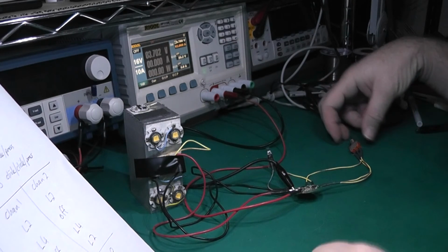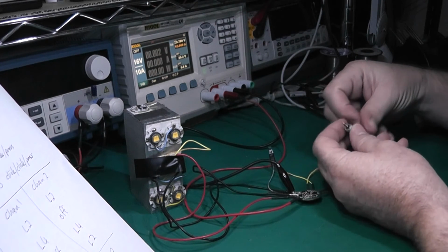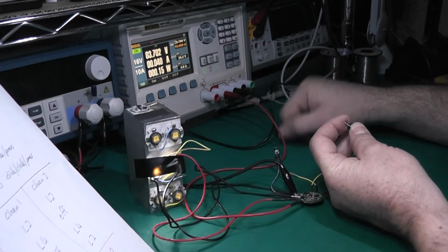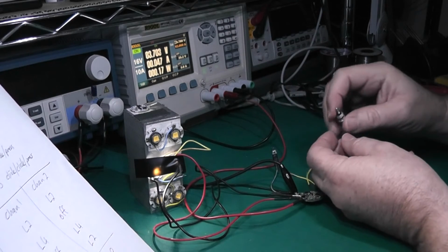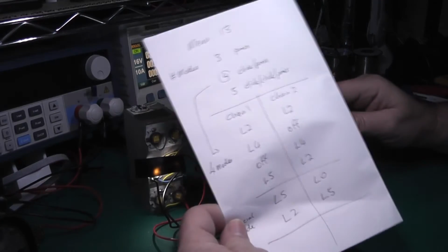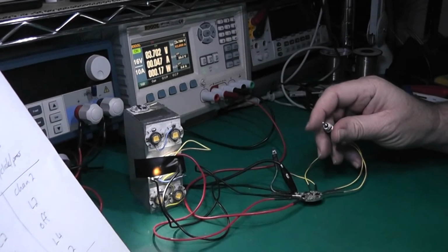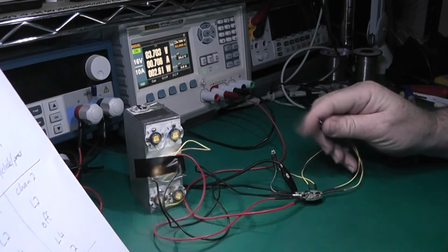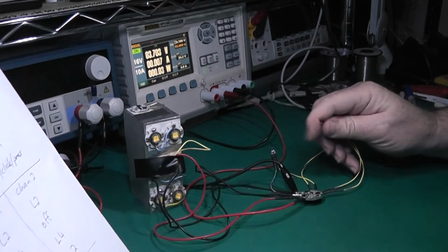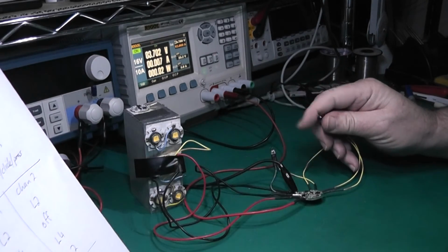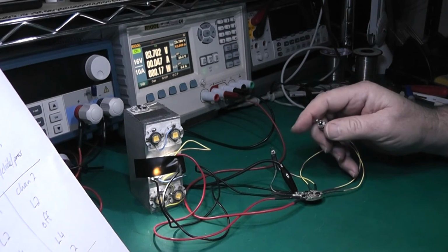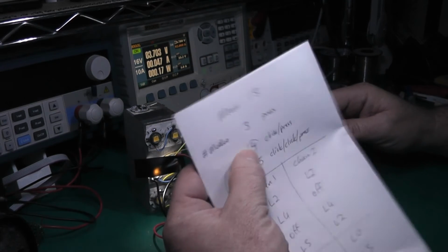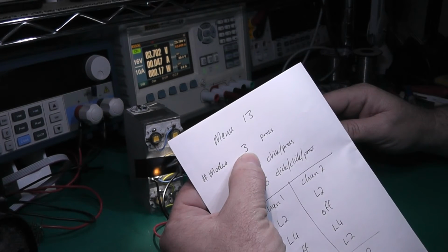So to get into the menu mode, we turn off the power, we press and hold the switch, and we apply power, flashes. We're in the menu system, so we want to program, remember, menu number 13, so we'll do 13 clicks, 1, 2, 3, 4, 5, 1, 2, 3, 4, 5, 1, 2, 3, and then press and hold. So now we're in menu 13, so if we just press at this point, we would have 3 modes.